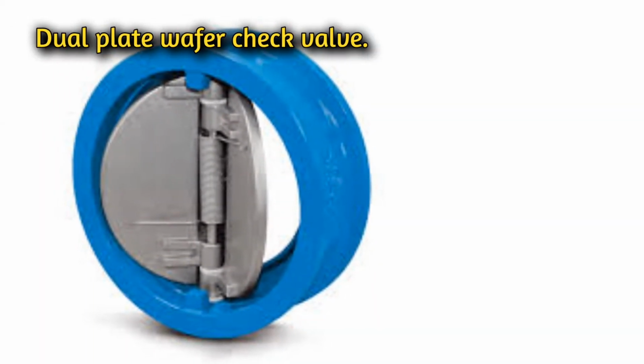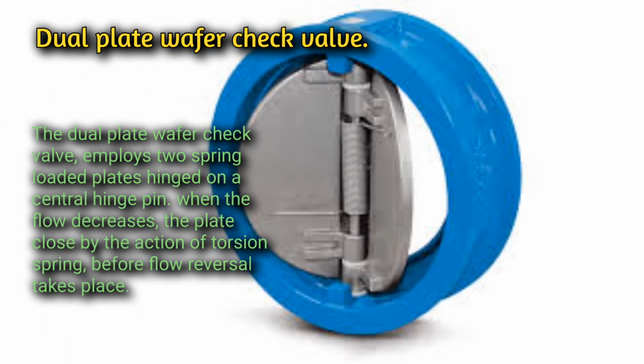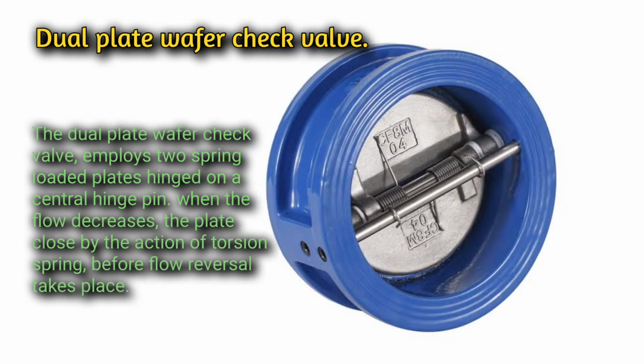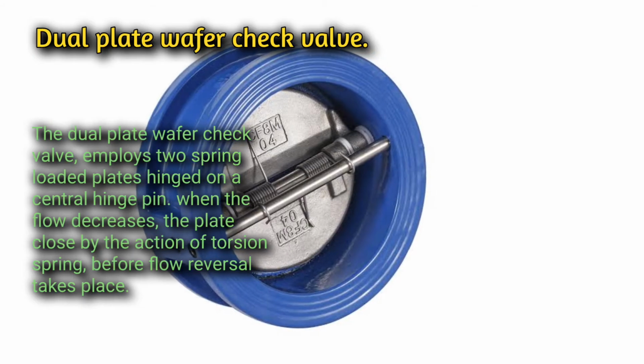Dual plate wafer check valve. The dual plate wafer check valve employs two spring-loaded plates, hinged on a central hinge pin. When the flow decreases, the plates close by the action of the torsion spring, before flow reversal takes place.